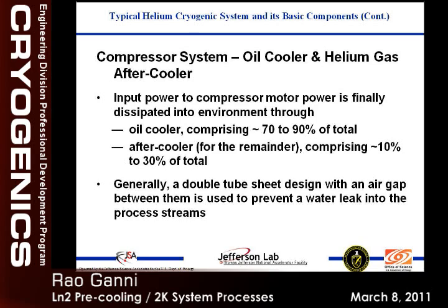We do not want water to get into the oil. It will end up in the cold box and it will freeze. Any leaks happening anywhere, whether you have a water leak or anything, it will plug the cold box. Now we have to trace back and say, where is it? Did it start at the compressor, or the brake cooler, or the turbine, because we use water to cool all these things. And everyone contributed on some system or other in some instance. So once the water leaks, you have a bigger problem on hand. So we take extra steps in designing these coolers so that the water leaks out, not into the oil, if there is a leak.